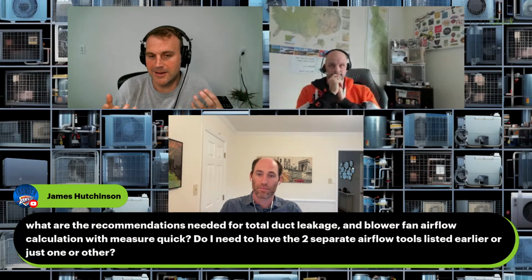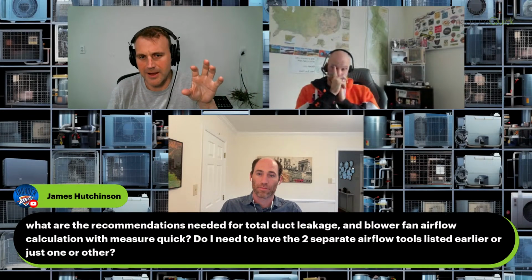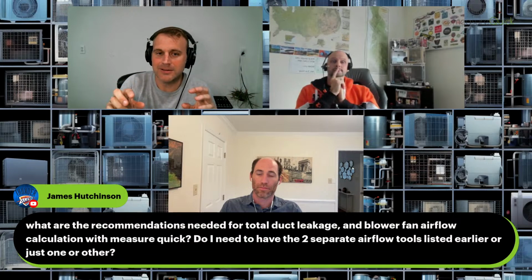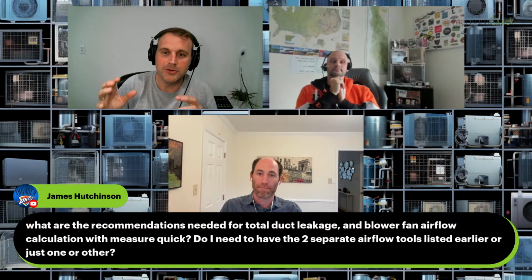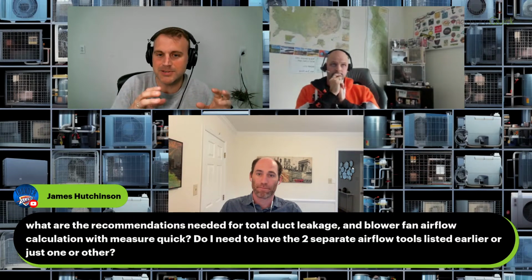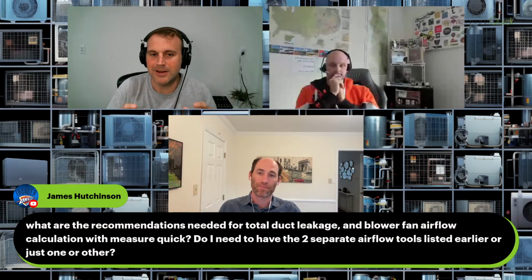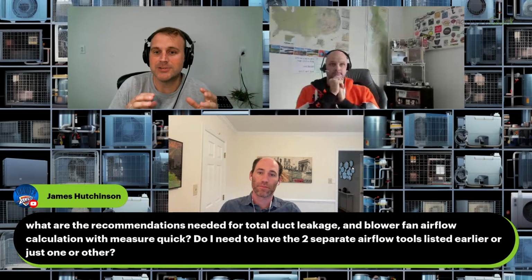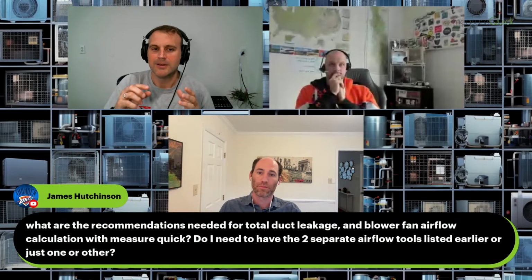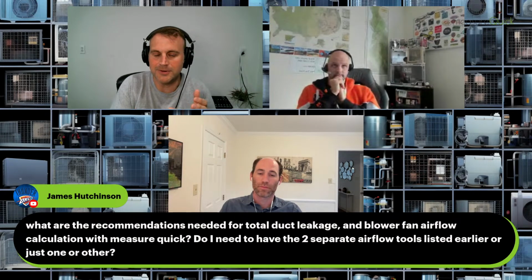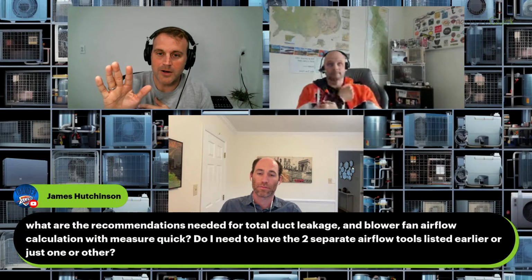But to dig into that a little bit, you can download the MeasureQuick app, and then the MeasureQuick app will let you activate the digital TrueFlow system, and you can use the TrueFlow inside the MeasureQuick app. It'll activate just like any other tool, right? And then when you activate it, now it's an app sharing tool, not a streaming tool. What that means is, in the app, when you want to use the TrueFlow to measure airflow, you'll click the button. Once it's been activated, you'll see it from the home screen on the gauge screen. You'll say use TrueFlow. What'll happen is MeasureQuick will pause, right?